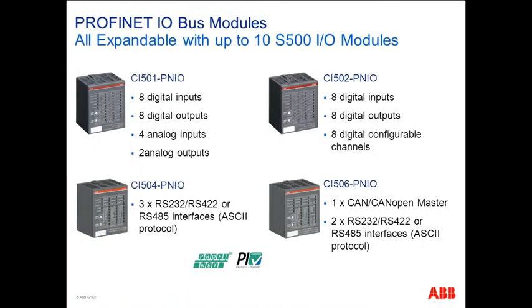What is seen now on the screen is the different PROFINET I/O bus modules. According to their specification, they come out with different types of built-in I/Os and protocols. Each I/O device could handle up to 10 I/O modules.